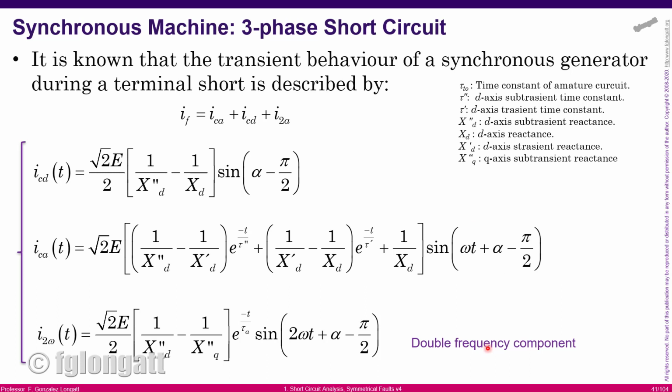I need you to understand there is a double frequency component in this real synchronous generator. And here you can see the double frequency argument inside the sine wave. I cover this topic about the double frequency signal on the synchronous generator current in my classes of advanced power system. However, at this moment, what you need to know is that this component is damped extremely fast. As a consequence, typically not many people take that into account.